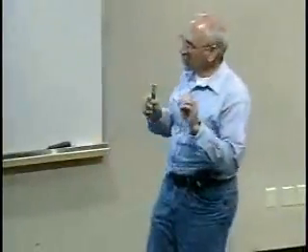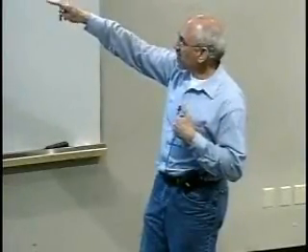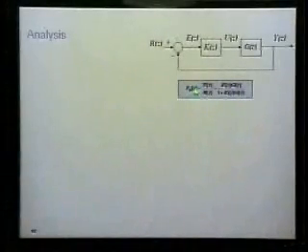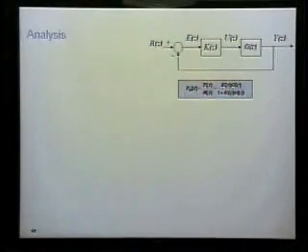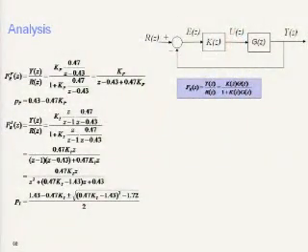So what the analysis is all about is figuring out the poles of this. Because as we saw before, that will tell us the settling time and stability. The other part of the analysis is that once we have this transfer function, we can evaluate this value at 1 and then figure out the steady state gain. And that will be our argument about whether or not it's accurate, or under what conditions. Okay, so here's what we got here. We'll take it a step at a time.